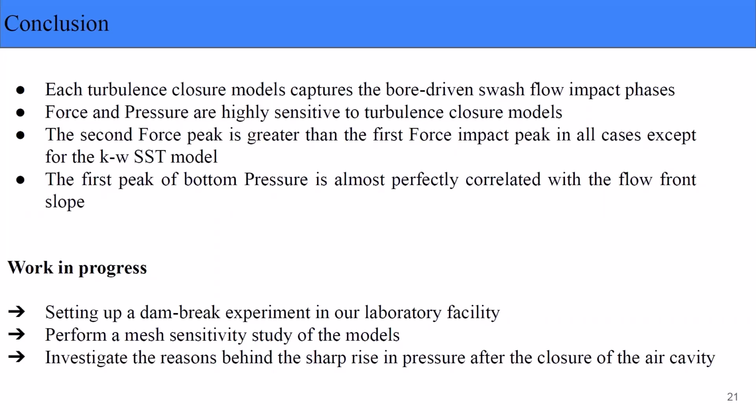So what we will do now is to perform in more detail a mesh sensitivity test, because we already did one and we are using a 2 mm mesh here in this case, and we have a Y plus of nearly 5. We are setting up a dam break experiment to measure these pressures and confront it with our findings using these three turbulence models. And we also want to investigate in more detail what are the reasons behind this sharp rise in pressure after the closure of the air cavity. So thank you.